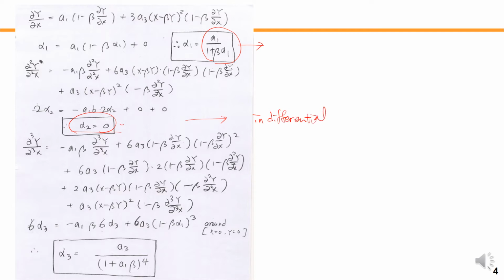So in a differential circuit, the dominant nonlinearity source becomes the third order rather than the second order distortion. So now let's find this third order coefficient. We derive all the equations around the operating point, so we'll get it like this. As you can see in this example, the original third order distortion coefficient was A3.